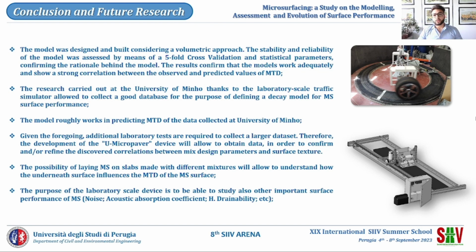Moreover, the possibility of laying microsurfacing on slabs made with different mixtures will allow us to understand how the underneath surface could affect the new layer. Finally, the implementation of this device will allow for a fast paving method, obtaining a small laboratory-scale test field for the study of other surface performances, such as noise absorption and drainability.